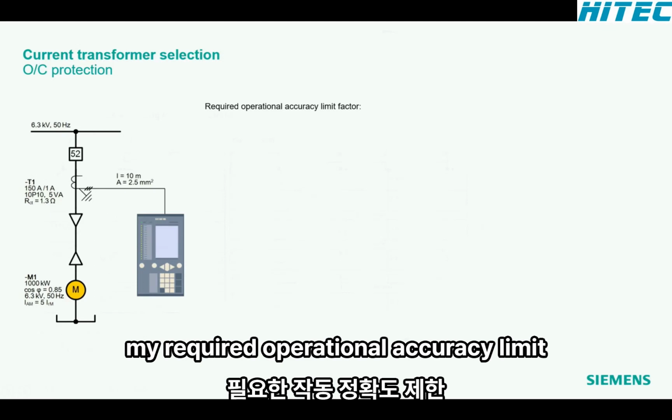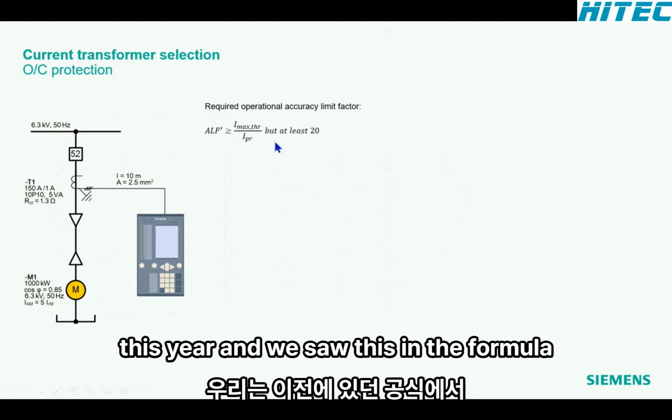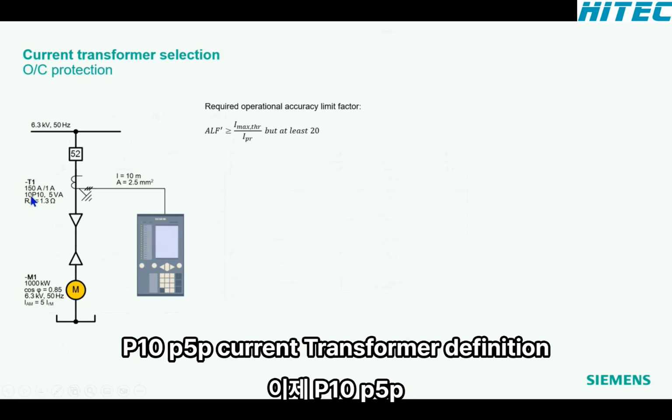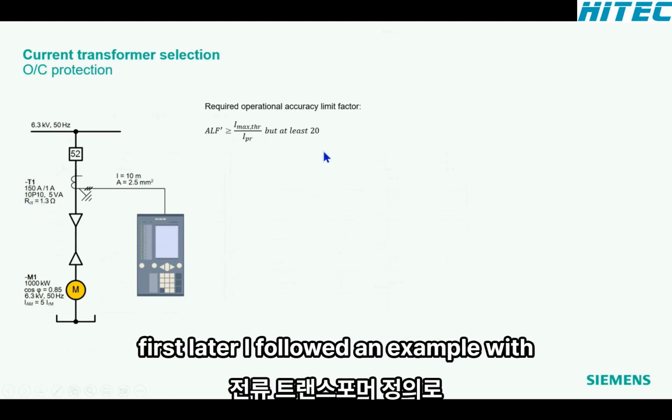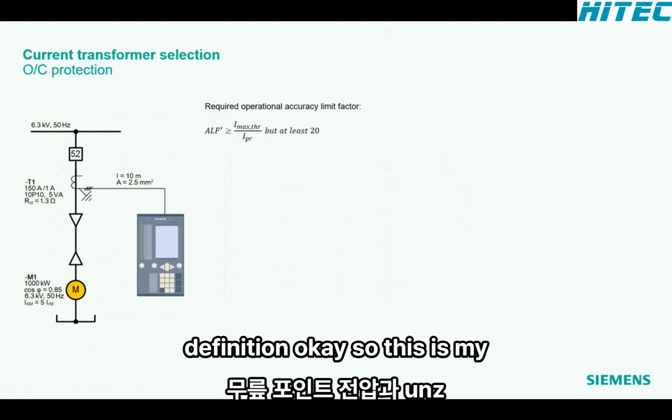My required operational accuracy limit factor is this here, and we saw this in the formula we had before. So I will now go for the P10, P5, P current transformer definition first. Later, I also have an example with the knee point voltage and with the ANSI definition. Okay, so this is my requirement.